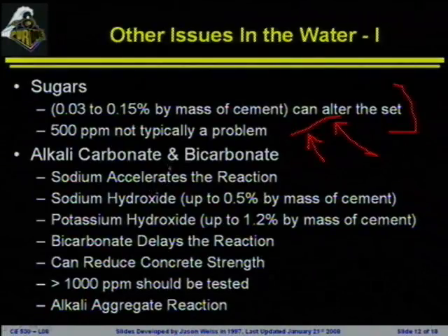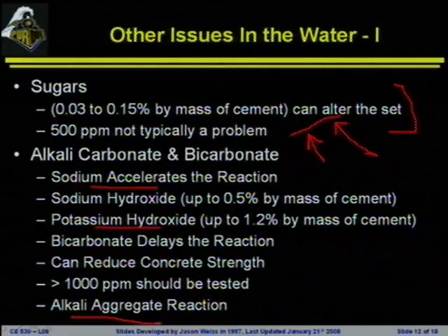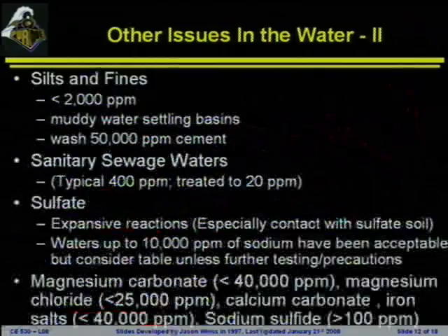Alkali carbonates and bicarbonates, sodium, it'll accelerate the reaction. Potassium hydroxide will accelerate the reaction. Again, you just want to keep an eye on this, because not only will it accelerate the reaction, but it can participate in a reaction with the aggregates down the road that can be detrimental.